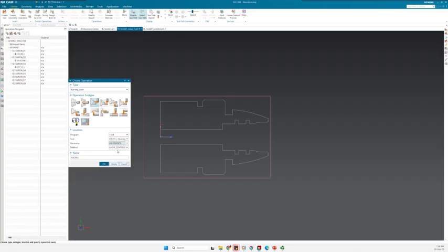After that, we are defining a lathe. So here is the same stuff that I was telling you. If you want to leave some amount of material for the finishing, you can define roughing now, put more material removal for the roughing so that you gain some time. If not, you can already do the finishing. It really depends on how much material you have left here. So this is something that I was able to define, but sometimes it's out of my control. For some stuff, the stocks are cut in an inclined way or something like that. So this is out of our control, or the shaft is too big, and then we need to gain some time. So we need to do first roughing and then finishing.